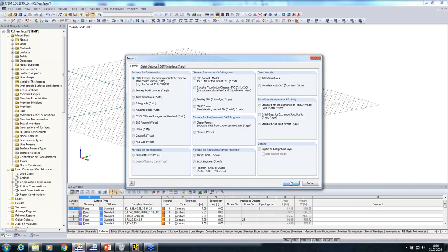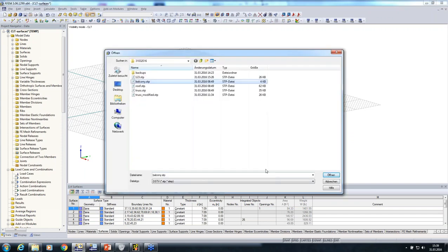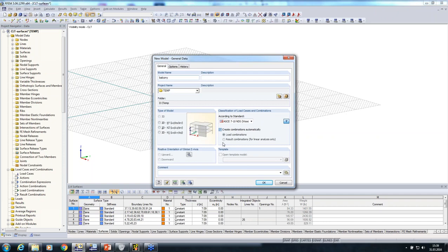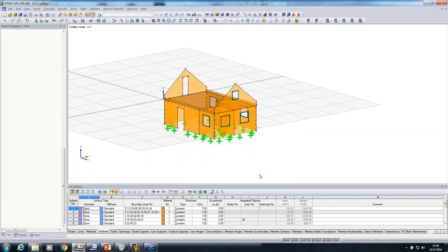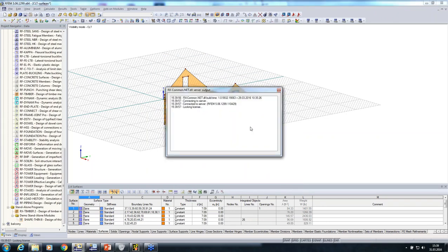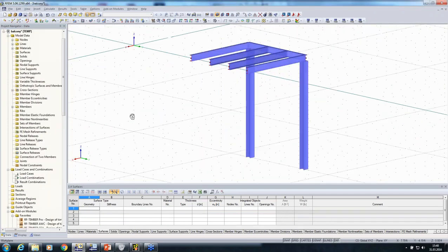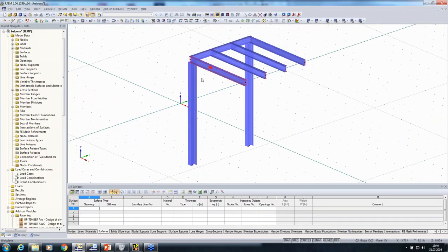It's also a wire.stp file, so that's the balcony. Import it. I don't need the automatic combination there because I just put it into the model I already have. So I have that also imported. The import right now is also with the conversion table for the columns, for the profiles. I just forgot to show it.